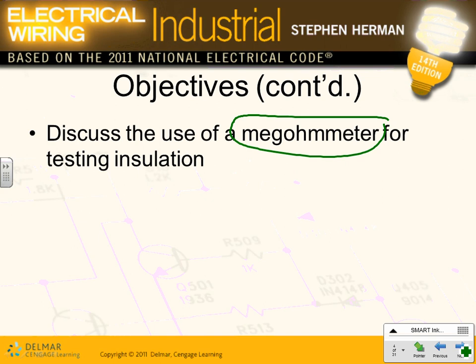While you're installing it, because Darren is kind of a tough guy, while he's pulling 500 kcmil conductor, he damaged the insulation. Now you have a ground fault in it. You can't tell unless you measure them. If you measure them, you take phase A that's grounded to the conduit, and it will show you very low impedance, low resistance. That's an indication, my friend, that you have a ground fault on phase A on that particular feeder.